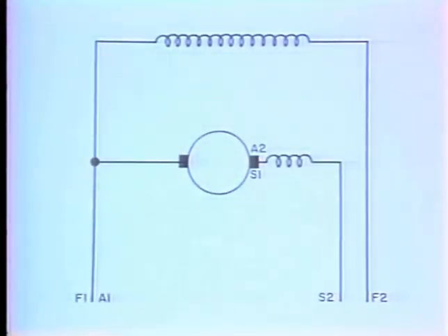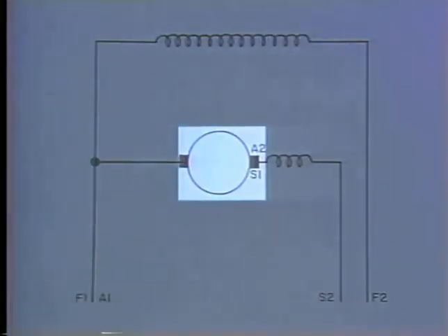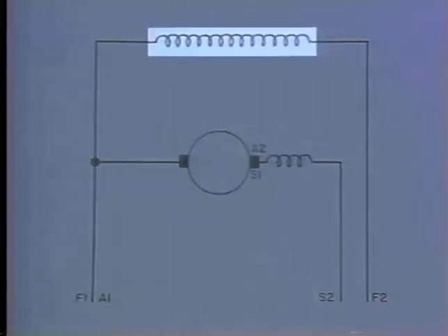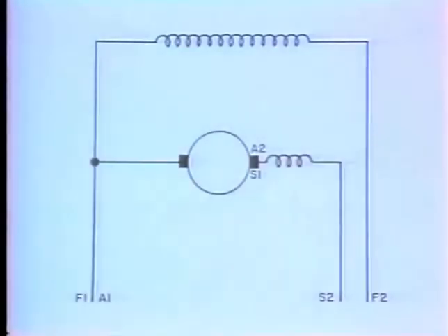To go any further, you have to break the circuit up and test one part at a time, eliminating the parts that are good so you can work on the ones that are causing the problem. According to the diagram, the ground could be in any of three circuits: the armature, the series field, or the shunt field. You can see what happens if we raise the brushes off the armature. We've got three separate circuits that can be tested individually.